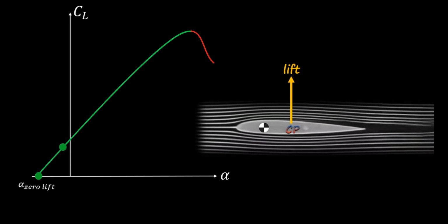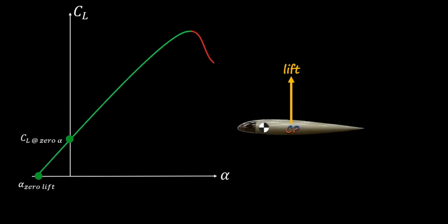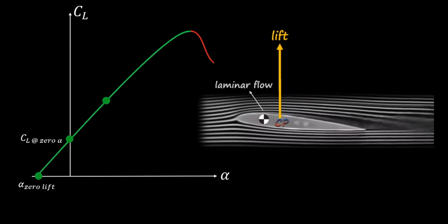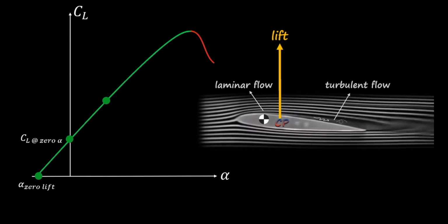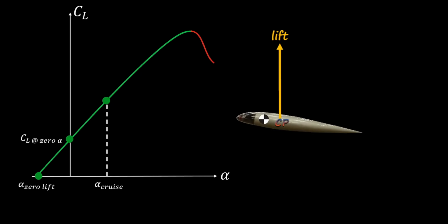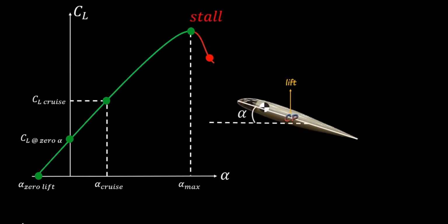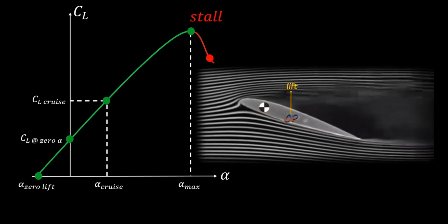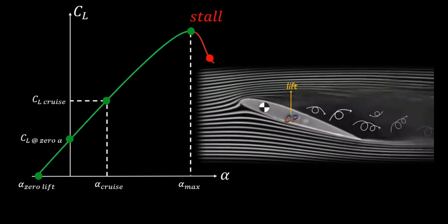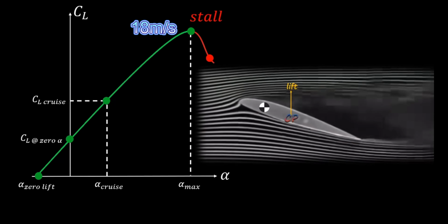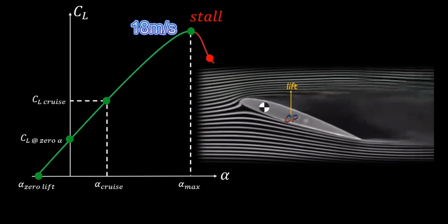In the takeoff configuration, it is necessary to determine the maximum lift coefficient, CL, that can be achieved within the critical stall speed range. When the aircraft pitches up, its speed naturally decreases. Regulations require the stall speed to remain above 18 meters per second. Although previous calculations with the improved airfoil gave a stall speed of 15 meters per second, we use 18 meters per second here as a reference to include a safety margin.